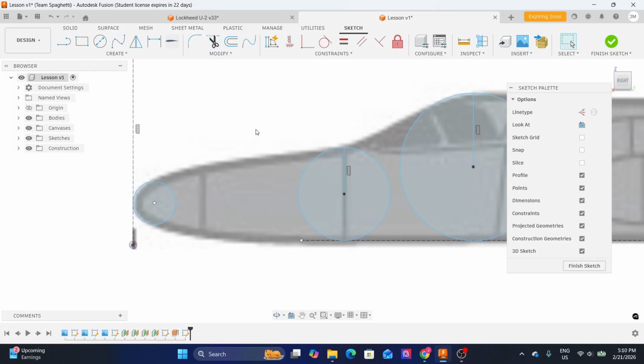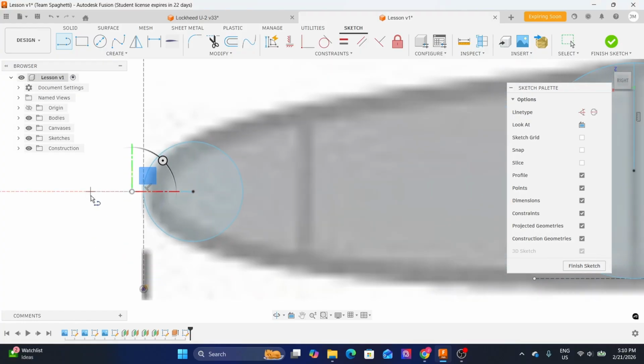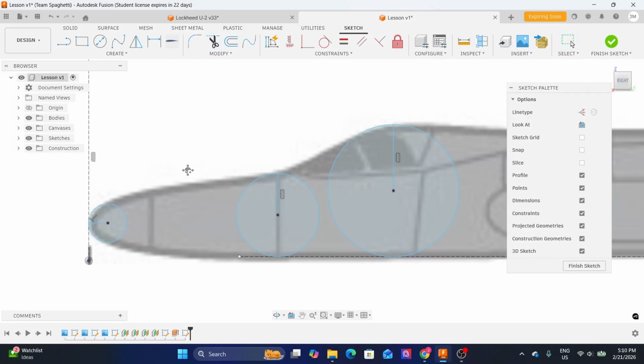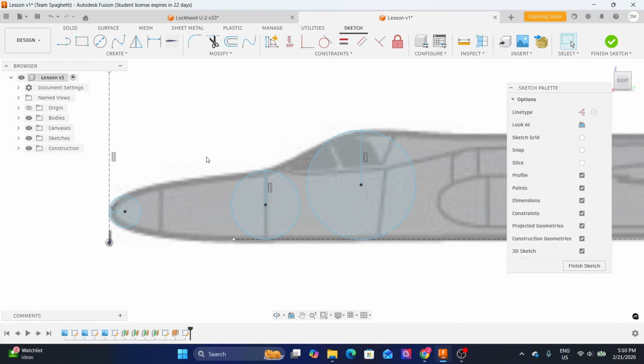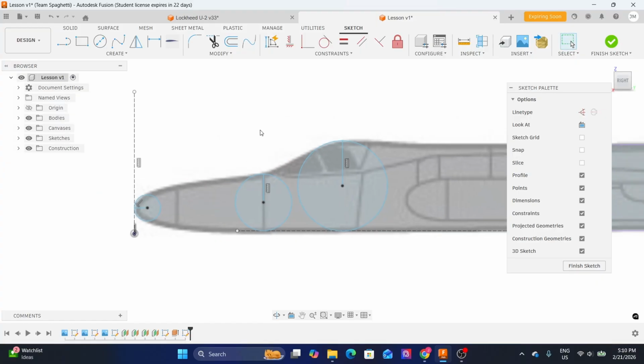Okay, and then line, or press L on my keyboard. This one, I would make this line as a horizontal line here. So L again, and then horizontal. There we go. And check. Escape on my keyboard. Trim the excess line. There we go. We have the construction circles and the lines inside them as well. So what I'm gonna do is I'll just batch select them, and then I'll be converting them into a construction line, the same as these two here.